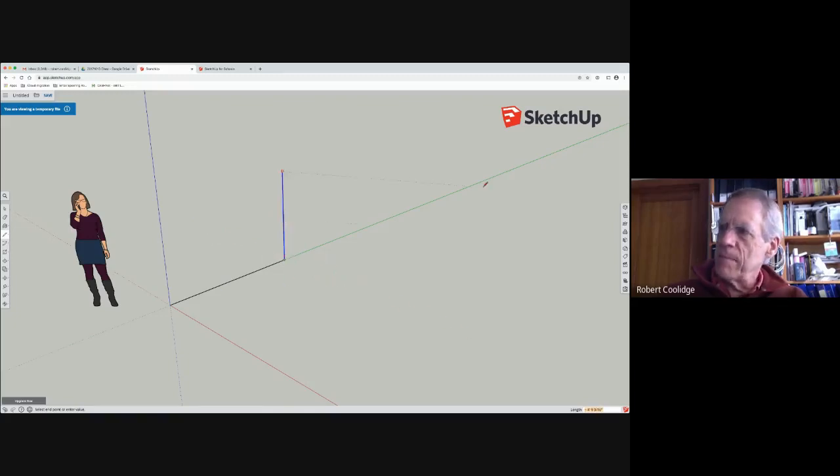If I tap the up arrow, it goes up. And it won't do anything else but go vertically as I draw. So for example, I can draw up here. I've now drawn a vertical line. It also does some smart inferencing. If I want to draw a rectangle that lines up with that corner, if I come down and hover the mouse over it, it says, you're looking at this point, aren't you? And as you drag up, it will align with it.